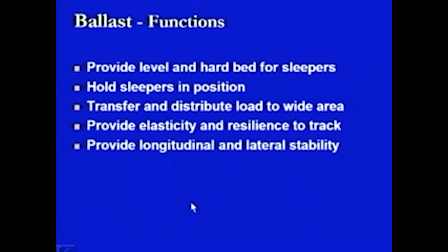Further, it should be able to provide longitudinal and lateral stability, that is going to be defined in terms of the amount of material which is being provided, and on the basis of that amount of material, especially the depth of the ballast cushion, the stability will be governed. So, this is one other function of the ballast.